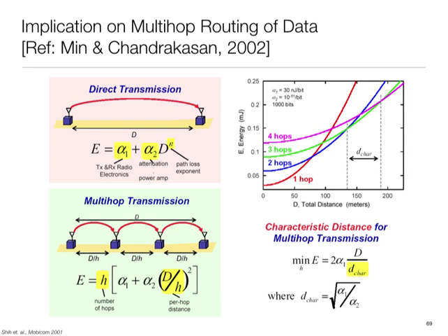So some of those issues play out, but sticking out here, a very simple radio model works. For transmit, it is some constant plus another constant times distance to some power. So essentially, I have three constants, and the receive one is even simpler. It's just some energy per bit. Now here I'm ignoring the fact that many radios give you control about the speed. So if there was a speed element, then there will probably be a speed dependent term also.